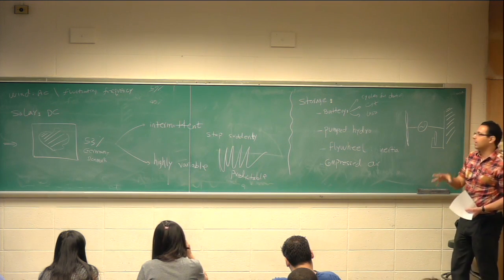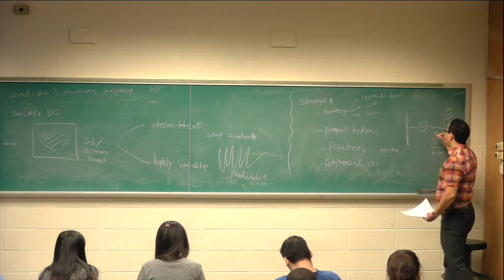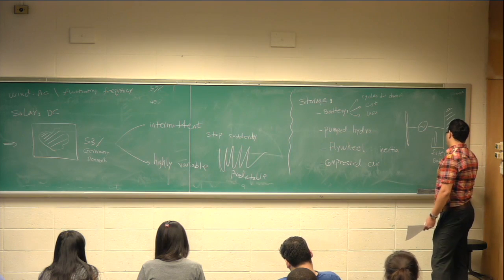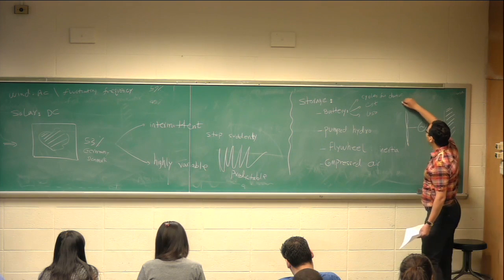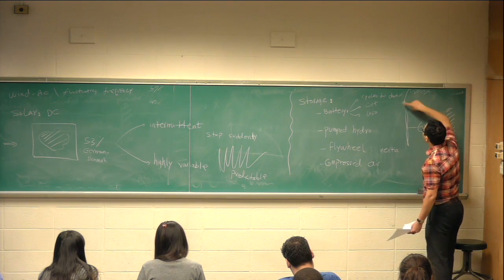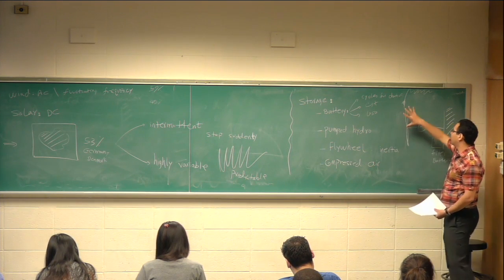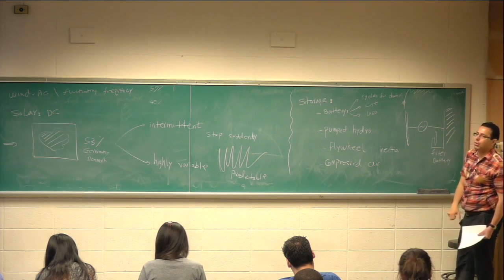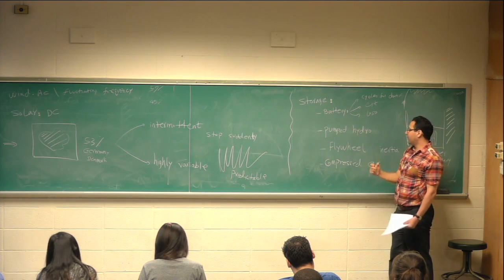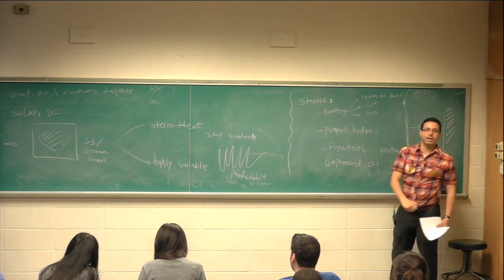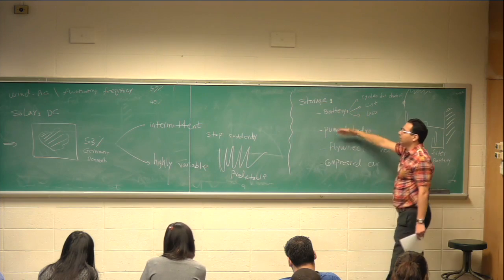And that's a flywheel. And that's regarded as a filter to filter out all harmonics, or as a battery, but it's a very unconventional battery. It works on the order of seconds. That deals with the high order fluctuation. And this is inertia. We go from fluctuating wind to inertia stored in flywheel. So this is about battery, this is about water, this is about air or pressure, this is about inertia. So we convert renewable energy to different types of energy.